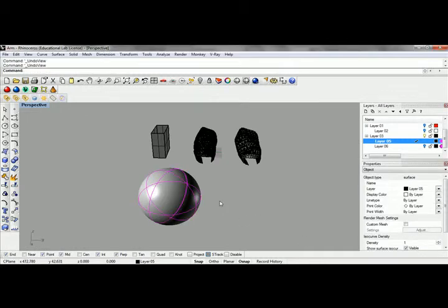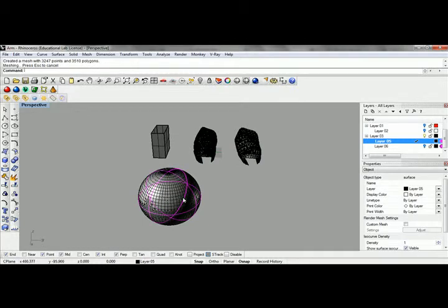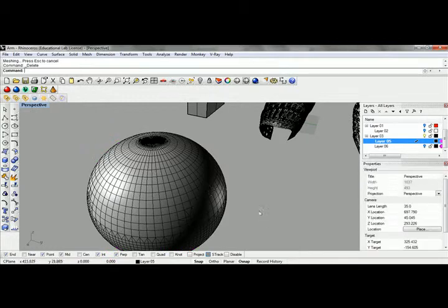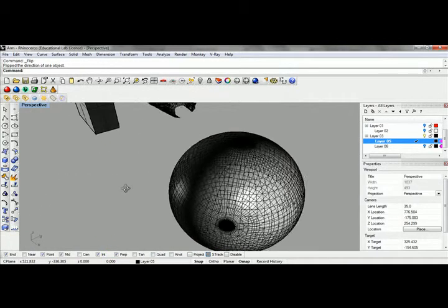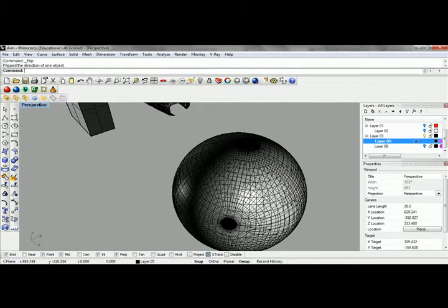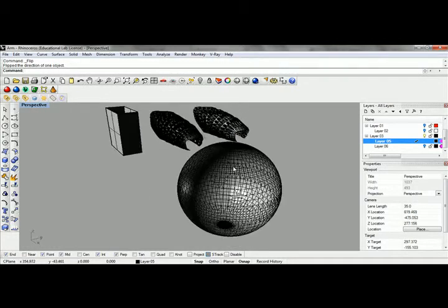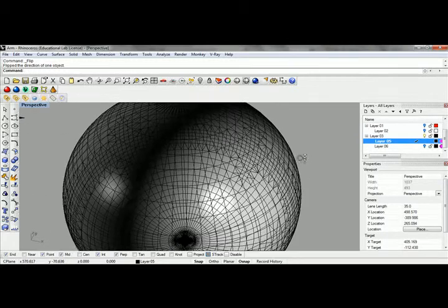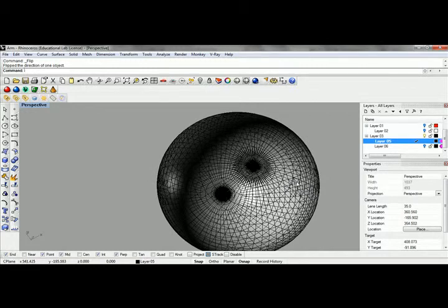Okay, so once we have these, if we have mesh objects that have problems, I'm just going to go ahead and delete that. You're going to discover that this one looks nice sometimes, and if we hit the invert button, some of your geometries, once you mesh them, are going to get confused. What this is doing is telling us that the front is actually the back, and the back is the front for all this. This confuses the machine when it gets into analyzing the tool.